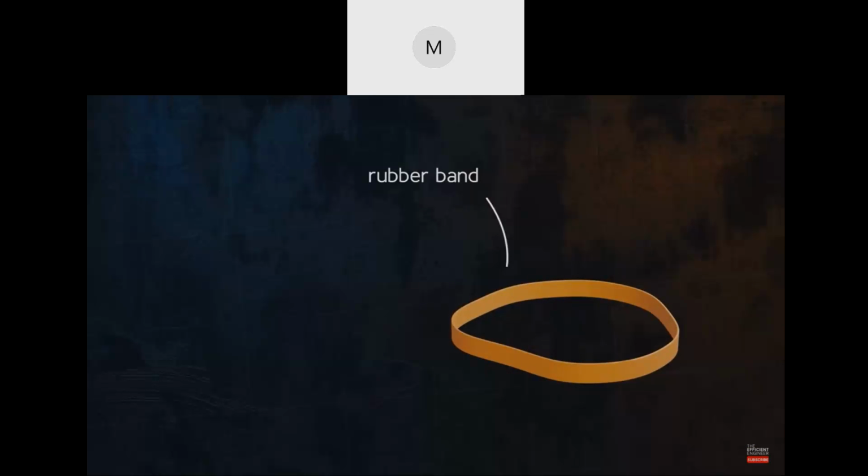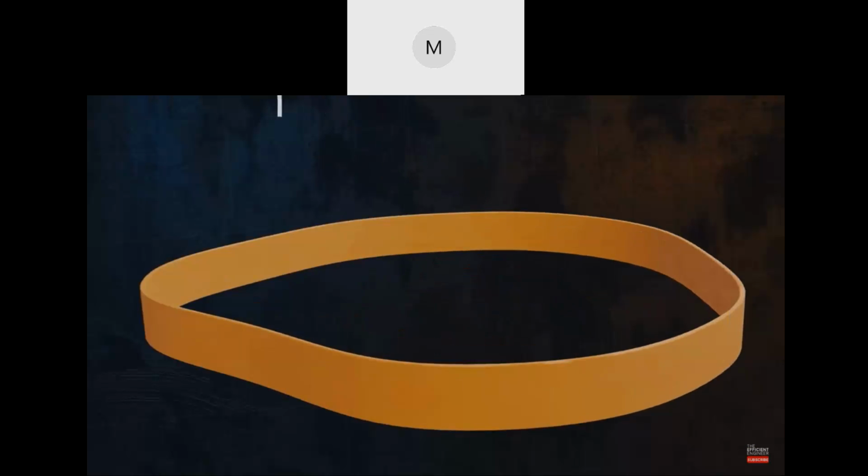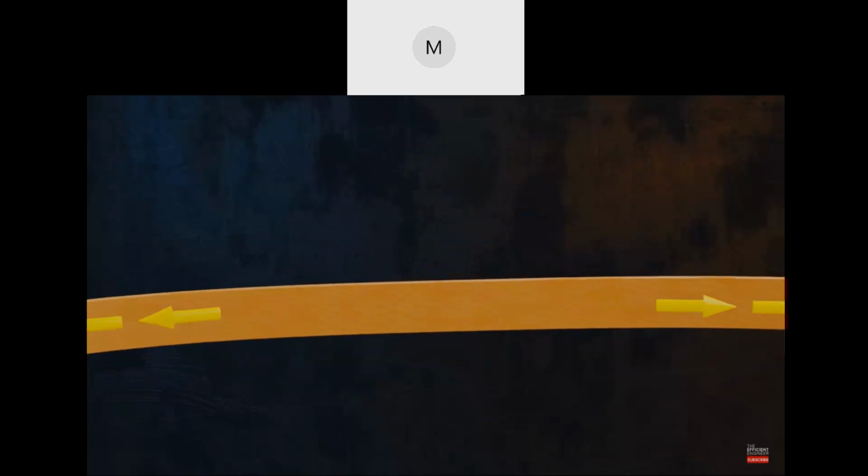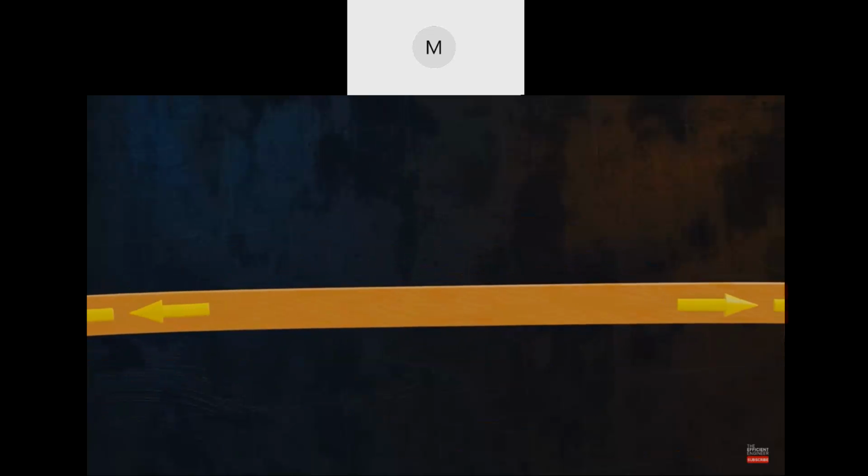We can start with a quick example. The rubber band. If you take a rubber band and stretch it, along its length it will obviously increase, but it is also quite intuitive that at the same time, the band will get thinner. Poisson's ratio can tell us how much thinner the band is going to get.